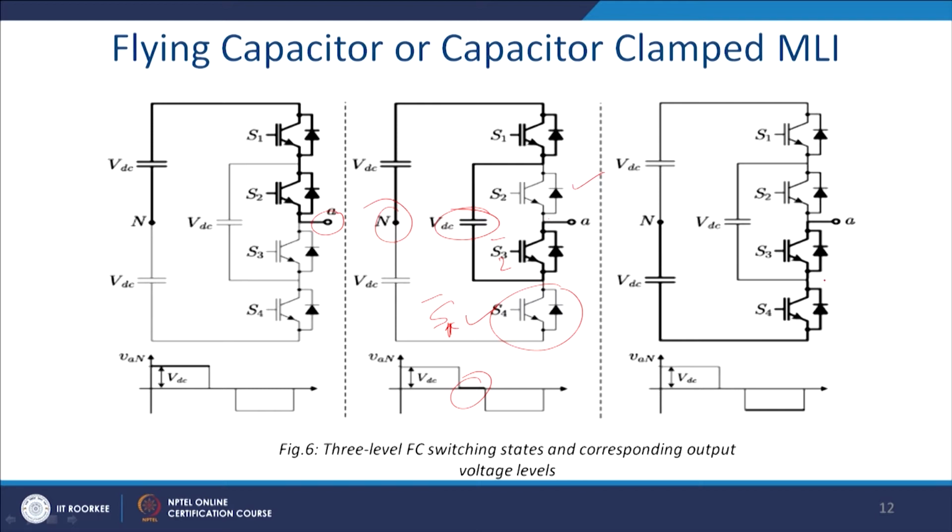and you get minus VDC. So, one of the advantages is that the component count is less. You generally made it with two diodes, here you have no diodes, only one capacitor, and you want to have a controlled voltage across it, that is one of the challenges, otherwise it works fine.